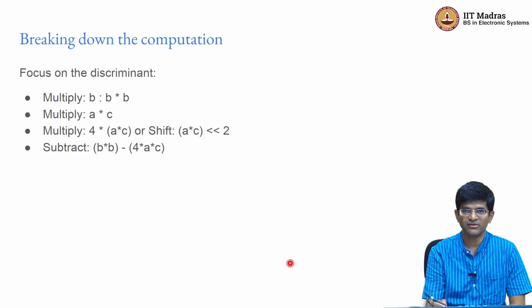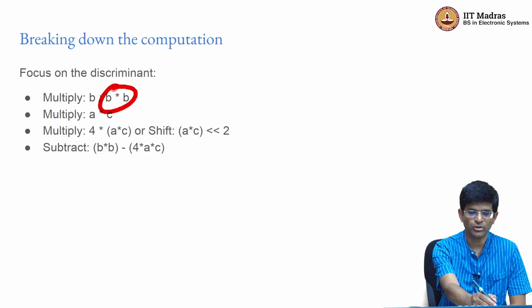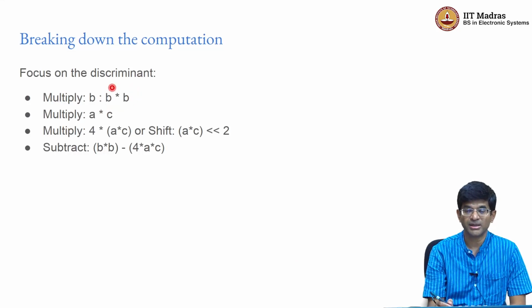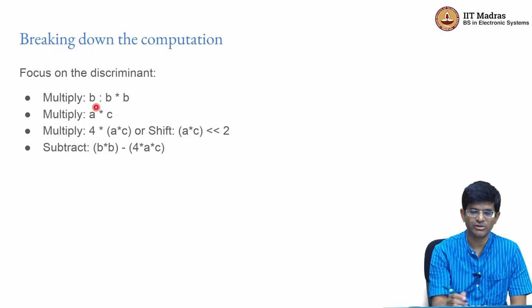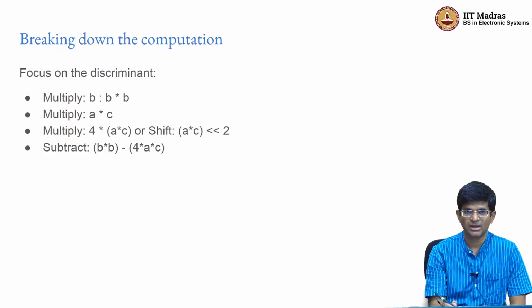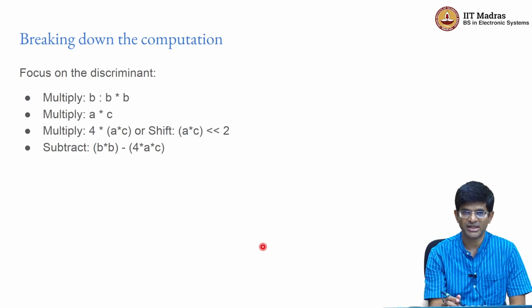So on the other hand, we know that by starting from Boolean algebra, binary arithmetic, we can go to adders, then we can go to hierarchical design, and then we can go to multipliers. So presumably I know how to build a multiplier hardware that can perform B times B. Okay, that same hardware can essentially also be used in order to perform A times C. And of course, over here the simplifying assumption that I am making is that I only want to multiply 2 elements at a time.